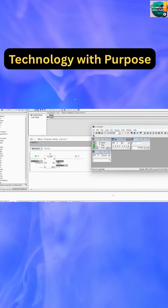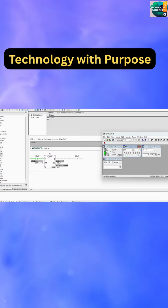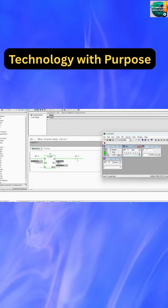Which means the output is on after 10 seconds from starting the timer by triggering M0.0, which means a delay time in turning on the output after the input is on. Hence it is called an on delay timer.